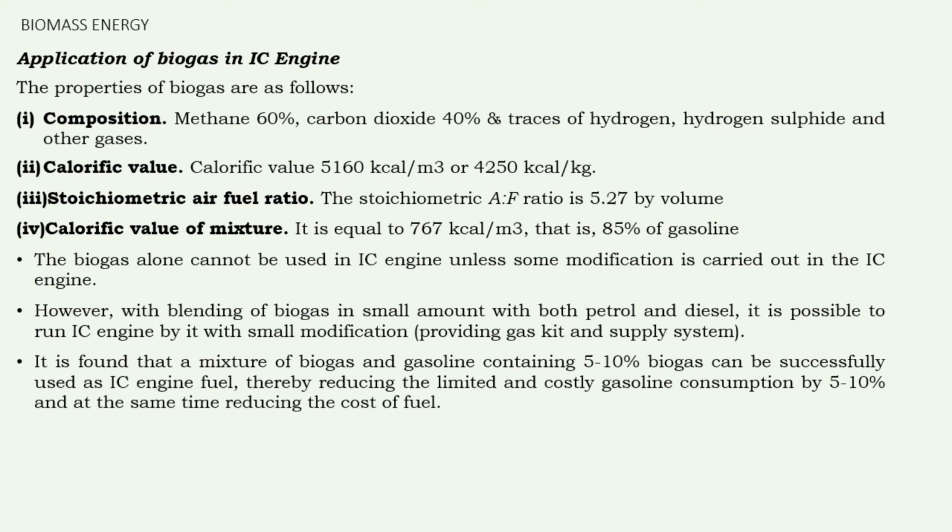Stoichiometric air fuel ratio is about 5.27 by volume, and the calorific value of the mixture is about 767 kilocalories per meter cube, that is about 85% of gasoline. So we cannot use this biogas directly in the IC engine.